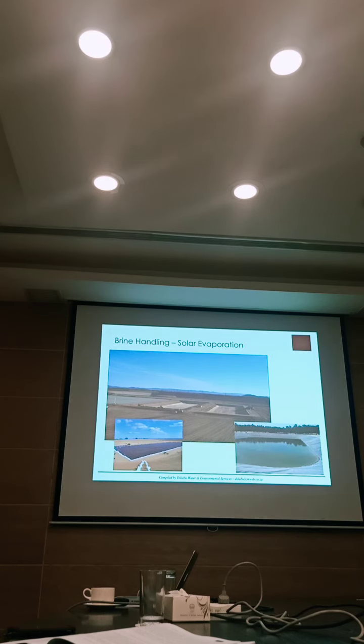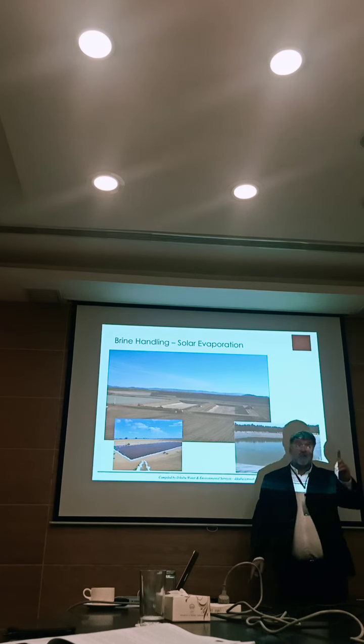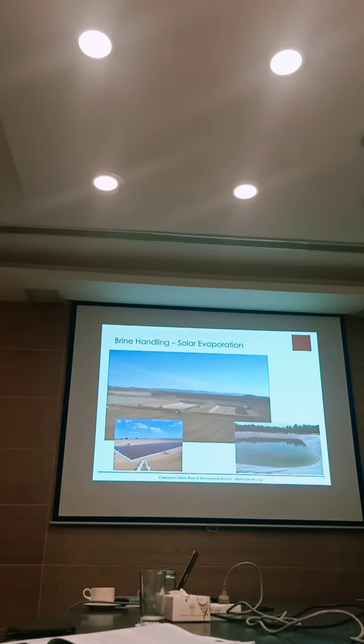Does it help? So what you do is that when you excavate like this, these are evaporation ponds. Then you come back and you put clay in there. You have to engineer it now. So you've got to compact it. You've got to construct your berms so that these can hold their shape and not have water passing through them, etc., etc. But the point is that it needs lining, and these liners are expensive.